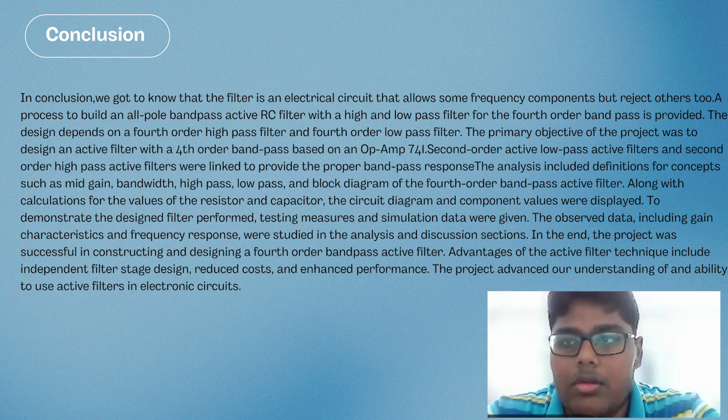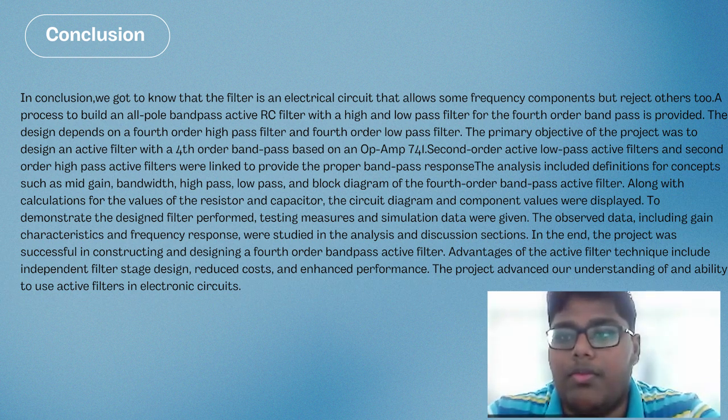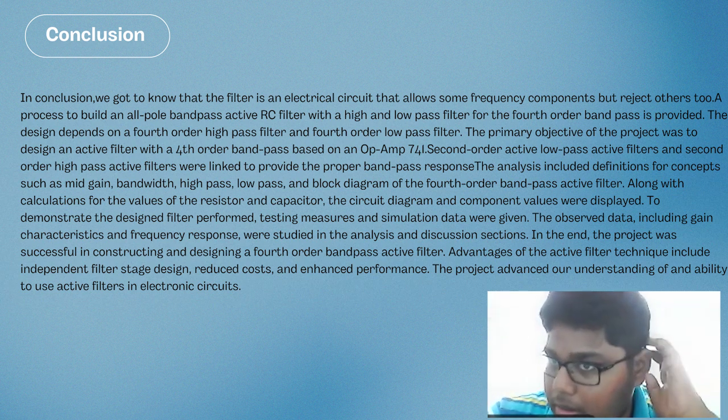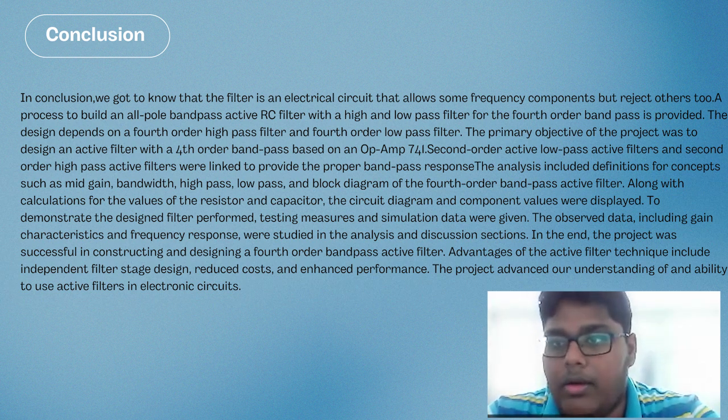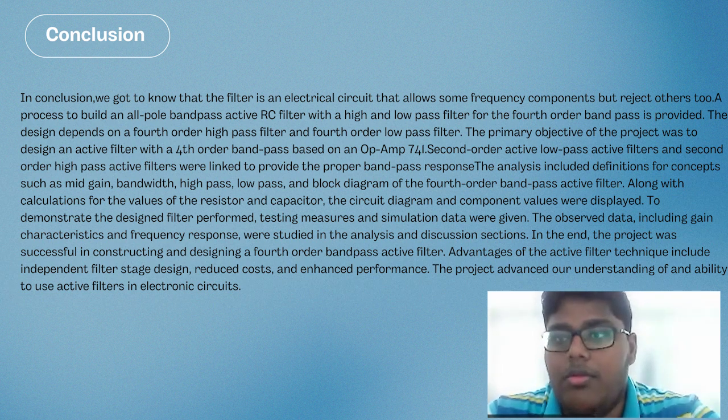And we got to conduct the experiment to find the mid gain, bandwidth, high pass and low pass values, and find the FL and FH values by doing the laboratory experiments and by simulation from Proteus. And we got to demonstrate the designed filter performance, testing measures and simulation data from the lab circuit that we did.